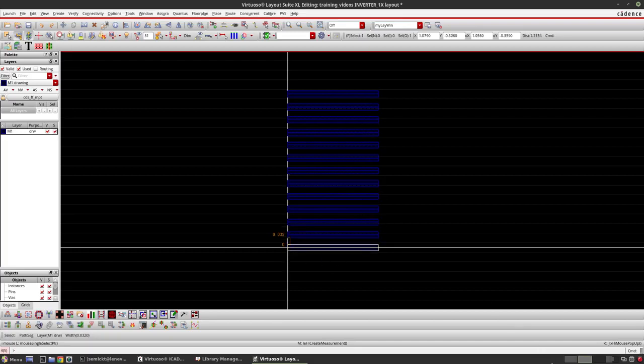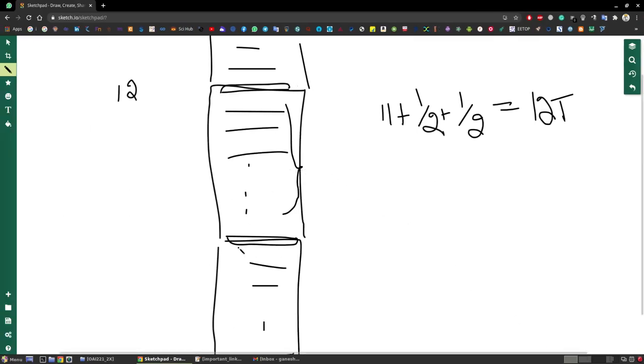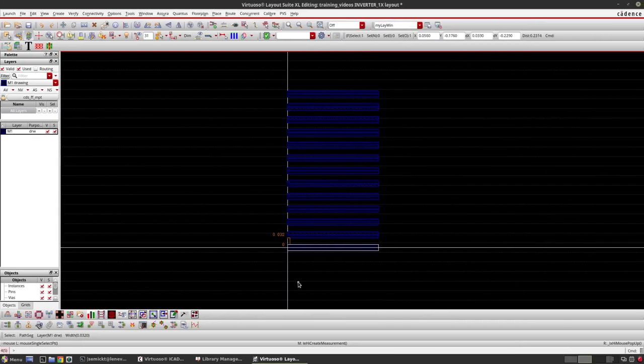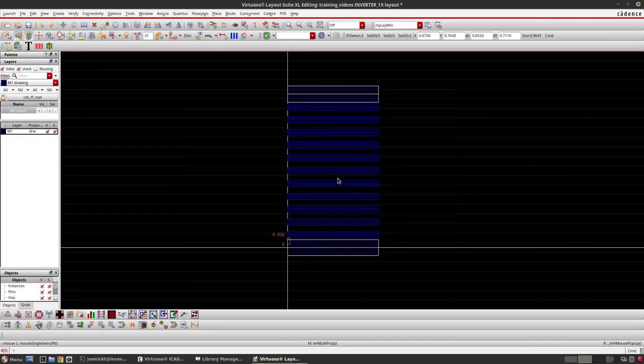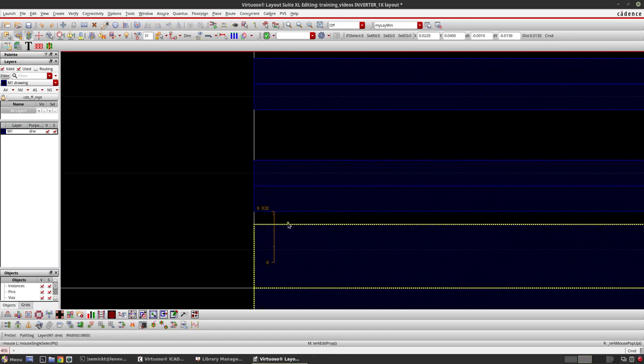Now as you had observed here, this VDD and VSS is going to be shared, right? So that means the current that is flowing here will be more. This VDD and VSS will be more. That means we should also increase its current carrying capability. Okay, that means we should make them less resistive, or in other words we should make them wider. Okay, for that reason I will be increasing the width of these two metal lines VDD and VSS to 80 nanometer.